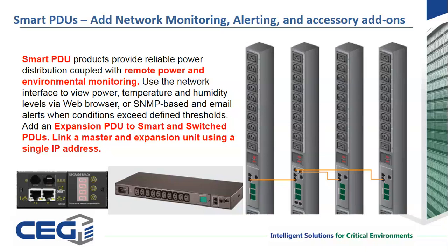That way, if you look at the example I gave earlier where you've got available outlets but not necessarily available power, when the guy plugs in the last piece of gear that gets you up to 24 amps, now you can have the alert sent out and management can take the necessary steps to stop people from connecting more devices into that power strip.